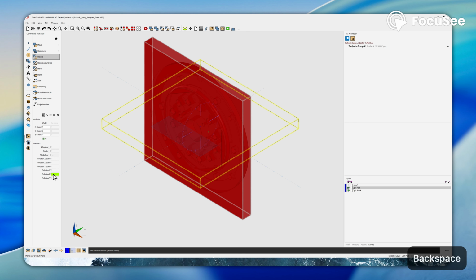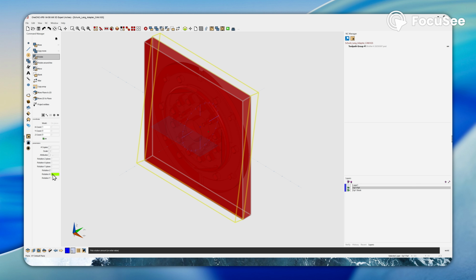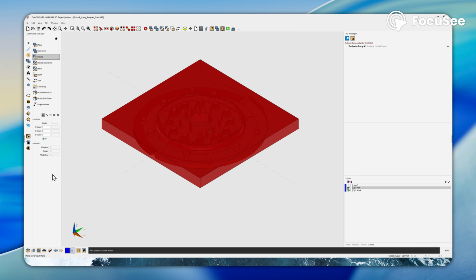Now, it auto-populated -90, but let's just go in here and put in a 0, and then let's just try. If you see, as I put a number in, -9, you can see that the part has moved from mostly vertical. The top of it has moved a little back, and that's the direction we would want to rotate it. So let's do a 90. And now you can see when I pressed enter, the part and the stock have both rotated in the direction I want. So I'm going to press escape to get rid of the rotation dialog over here.